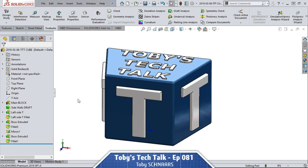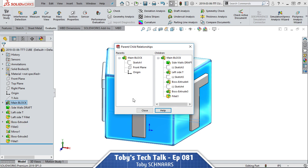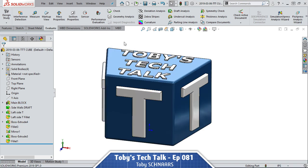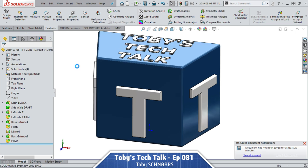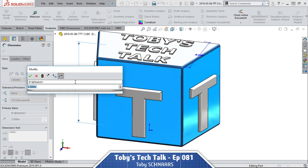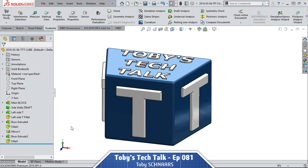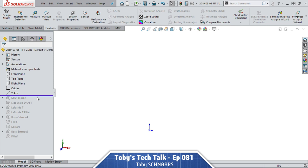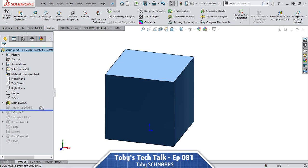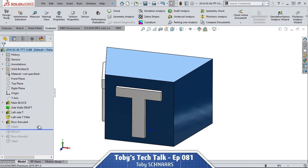And what that rebuild light indicates is that that feature and any child features that are related to that feature are going to need to be rebuilt. So what that means is if we go up and we hit the rebuild light up top here, or if we hit Control-B, Control and the B key, that feature and any child features will be rebuilt. Changes back to 2 inches. And then I'll hit Control-B again for rebuild. Now, another command that was in that list was Control-Q. And Control-Q is a little different. What Control-Q does is if we roll back to the beginning of the tree and then we start moving forward and we were to kind of rebuild each feature along the way, that's more of what Control-Q does.